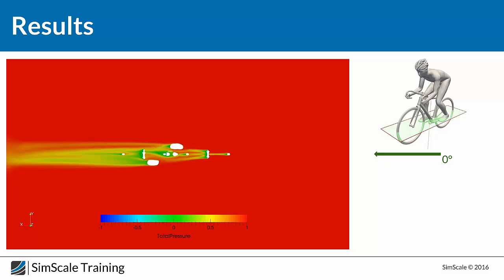If I jump to the next slide, we can see that something changed, and it's the size of the tire. Now we are talking about the mid-size tire, the mid-thickness tire. If I jump back, you can see that we have strong separation over here, and for this one the separation is reduced a bit. It's not really significant, but it's reduced. So we can say that the thickness of the tire can dramatically impact the performance of the tire in terms of drag.